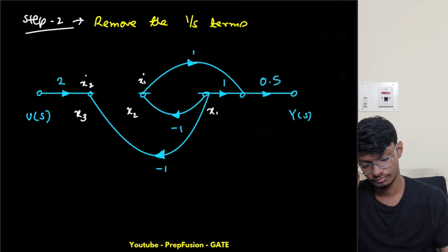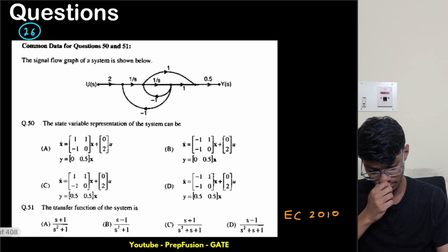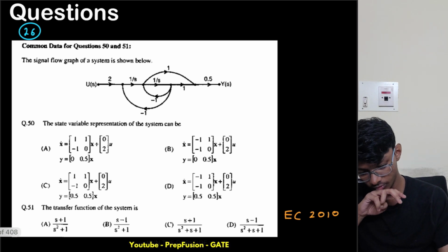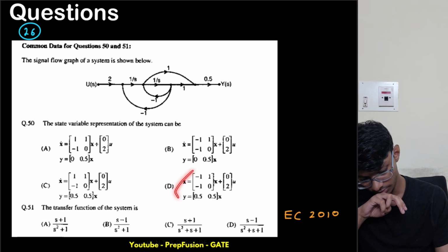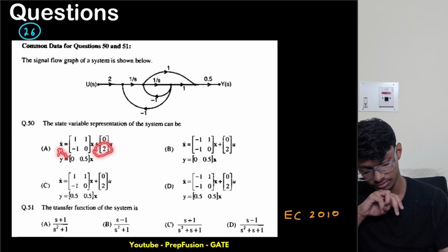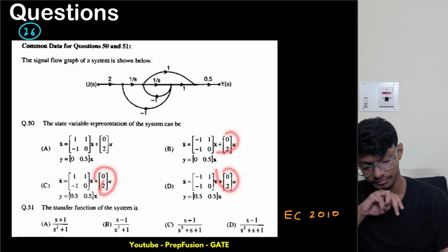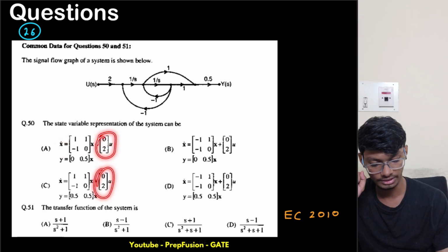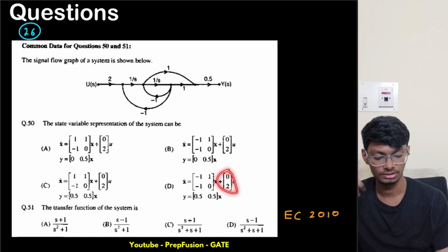So what I will do, simply write the equation like this one. One more thing you can notice over here, look, they have changed this one. One thing that is constant is this one, right? The 0 2 is constant, the 0 2 is constant. So here will always be a state variable, either x2 or x1. They have given x2 as this one, 0 2. From here also I can understand this is x2 dot, because this x1 x2 comes in the bottom. So here our row and column will be interchanged, right? From this you can take the hint what to choose as x1 and what to choose as x2. This is a big hint, right?